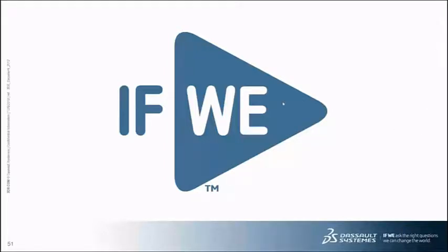Can you talk about symmetric versus unsymmetric solver? Yeah, so I didn't mention that, but what happens when you're doing contact modeling and you do the linearized structural stiffness, it turns out that that's a non-symmetric matrix equation, and if you're only storing the symmetric part of it, you may not be able to produce the required corrections. If you are using the symmetric solver, which considers the linearized stiffness to be symmetric, then if everything converges, you're okay. So you're not producing the wrong solution. But in some cases, you may need to use the unsymmetric solver.